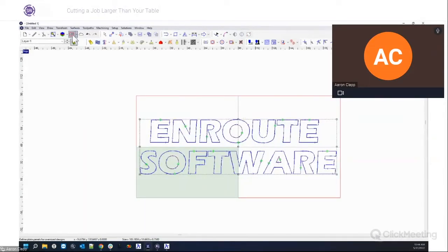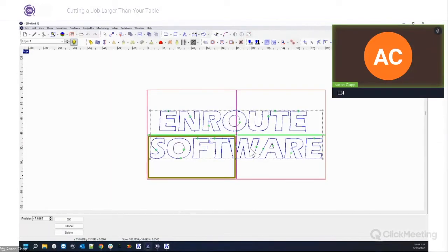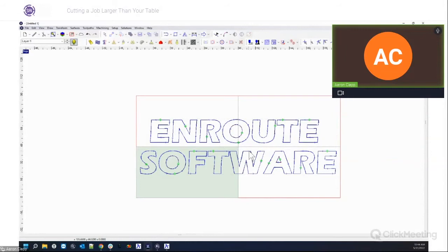And then I'm going to come over here and do it again. Click on this guy, hit F2, and I'm going to change this one to 48. I want it to be halfway in between. Okay. And that allows me to put it at whatever coordinate I want to. So it's really accurate. That way you can put the dividers wherever you want them to be. So in this case, I've got 48 by 96, or 4 by 8 panels here.